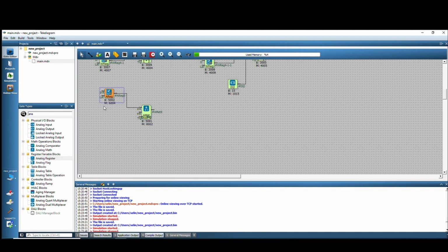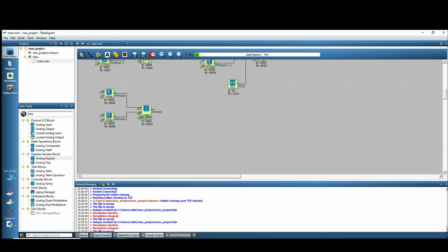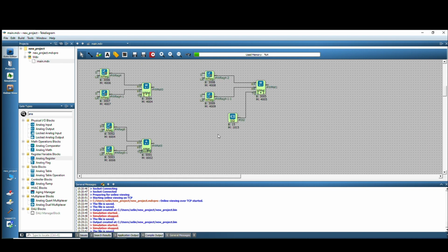A word register should be connected to the INA input of the block. This operation is performed at each PLC cycle by default. If the on when trig is active option is selected, this operation is performed at each rising edge detected on the TRG input of the block.